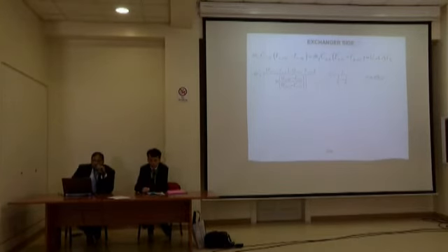So the aim of this paper is to compare 4 different configurations in order to decide which one to use. The configurations were chosen based on the available requirements in the project. The outdoor conditions were chosen for Doha, Qatar, which are 46 degrees C dry bulb and 31 degrees C wet bulb. This has a humidity ratio of 22.2 grams per kilogram.